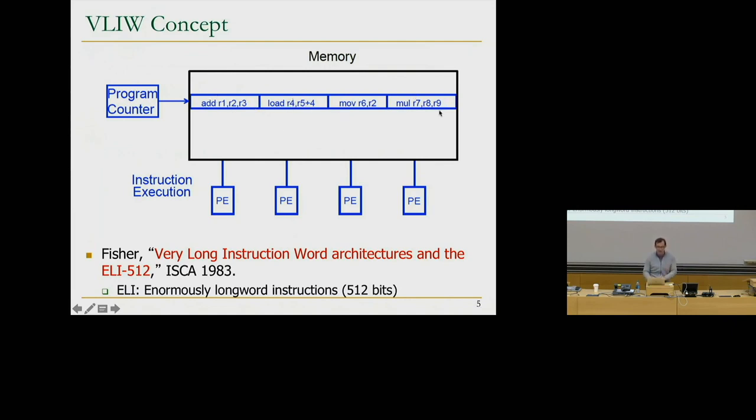If, for example, you put the load over here, and if the load execution unit was here, you need to somehow route that load here. But if the load execution unit is here and the compiler is aware of that, and the compiler puts the load over here, you don't need to do any routing logic in hardware. There doesn't need to be extensive wires to move one instruction to the processing unit that can process it. Does that make sense? So the compiler is the master here. It does all the scheduling, and we'll see a couple of examples.